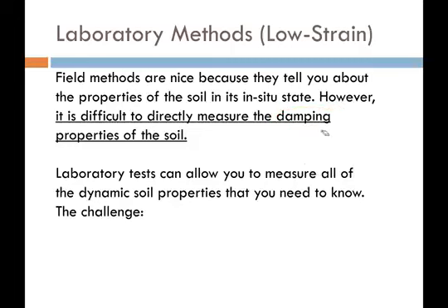Really, in my understanding, which is limited, really the only way we can get damping is through the surface wave geophysical methods. And so one of the best ways that we can have to measure the damping properties of the soil is to get the soil into the laboratory where we can do some more controlled testing of it.